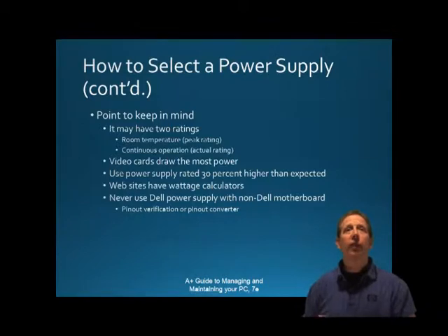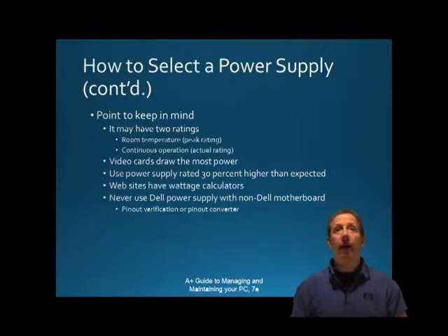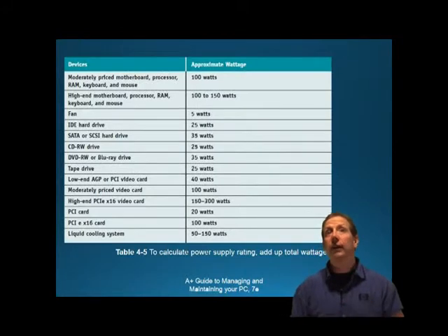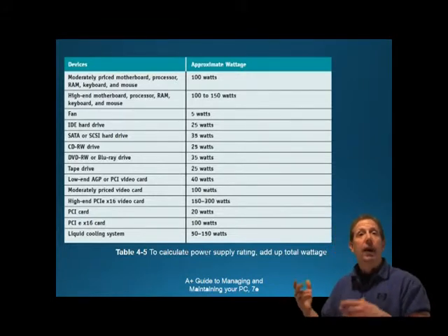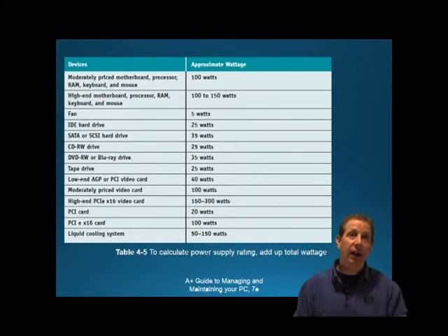Point 4. The websites of some power supply and motherboard manufacturers have a wattage calculator where you can enter the components in your system, and then the calculator will recommend the wattage that you need. You will see one example of the wattage calculator in Project 4.7 at the end of the chapter.